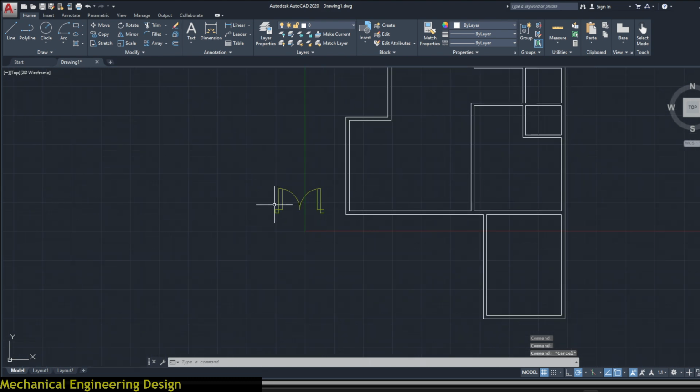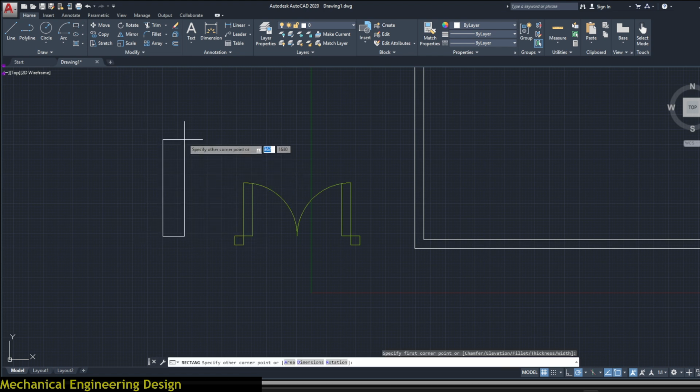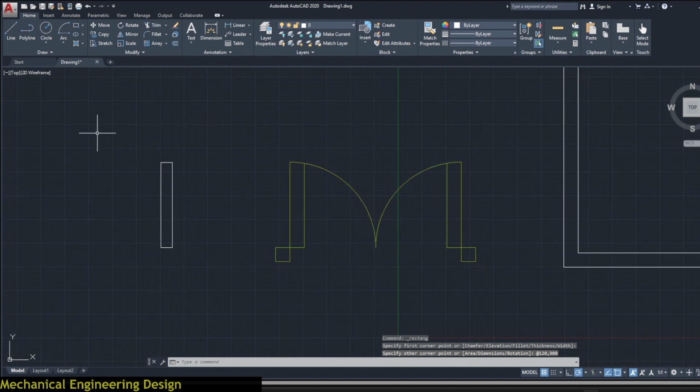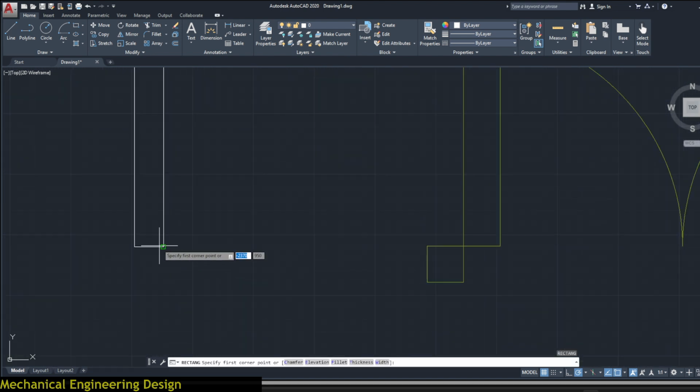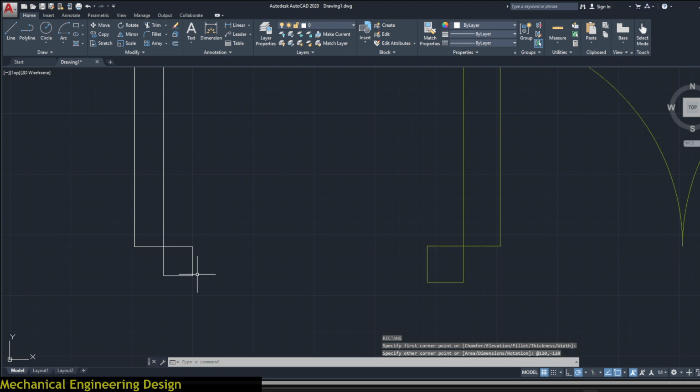We create another block to represent internal doors. Pick on rectangle, click on first point, base of 120, click on tab, height of 900, enter. Enter again to repeat rectangle from this point, base of 120, click on tab, and then negative 120, enter. Select the larger rectangle and explode.